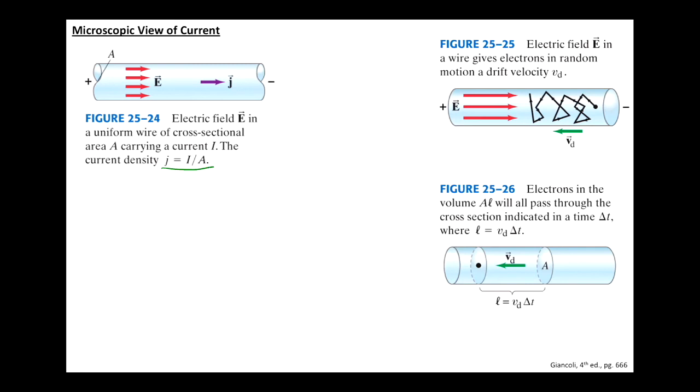First of all, it's written right there, but I'm going to write it again. The current density is equal to the current divided by the cross-sectional area. You could think of I, the current, as sort of being the bulk value. It's how much total is passing through the wire or through the conductor at a point. J is more like going to different points within the conductor and asking how dense the flow is at that particular point in the conductor. The current density is the total current divided by the cross-sectional area. We can also relate this to the electric field by another quantity we learned about today. So we could say that the J vector is equal to the conductivity times the electric field.